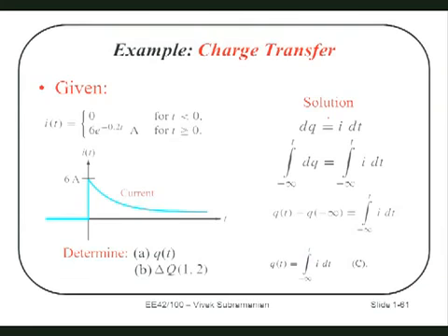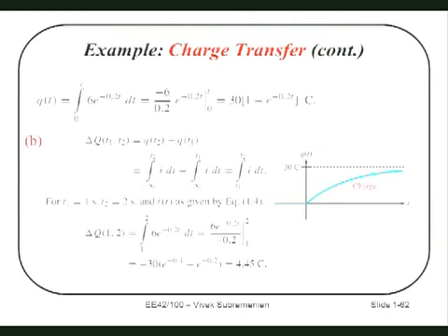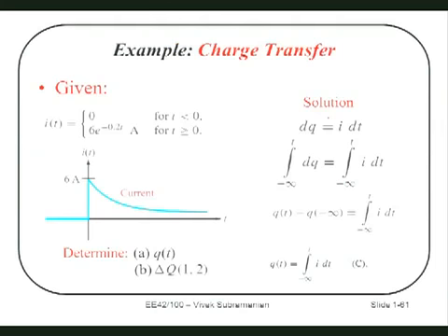So, I take the equation. Life gets easier because, sorry, I should have left that on the board for a second. Life gets easier because I said I is equal to 0 for all t less than 0. That fact allows me to make my life a little easier. How? Because this minus infinity integral now becomes an integral from 0 to t. Because less than 0, I is always 0, which means all values less than 0 I can ignore.